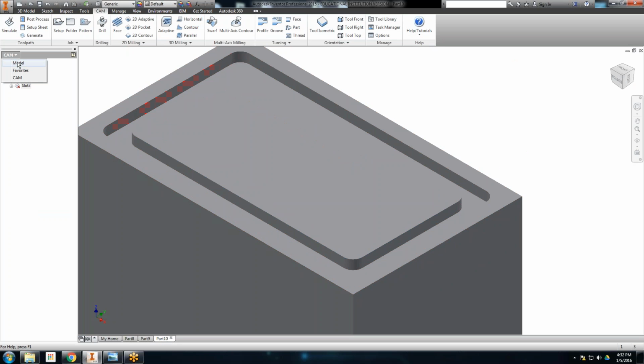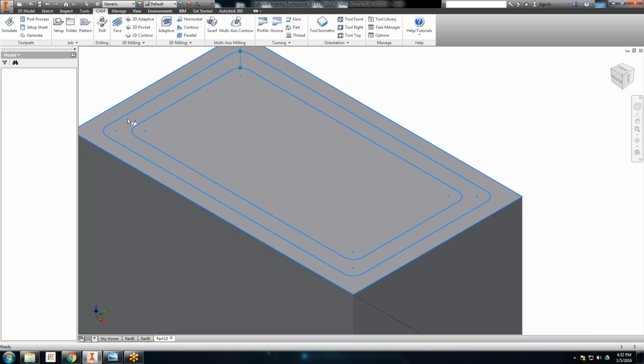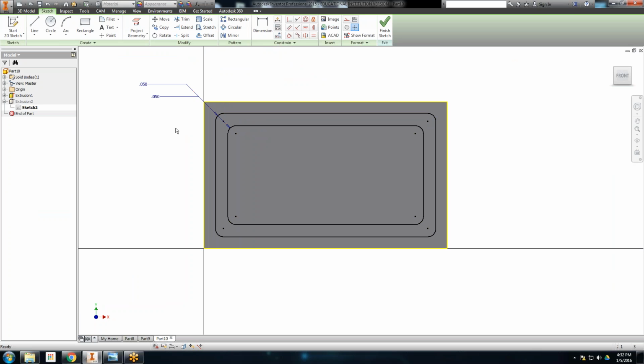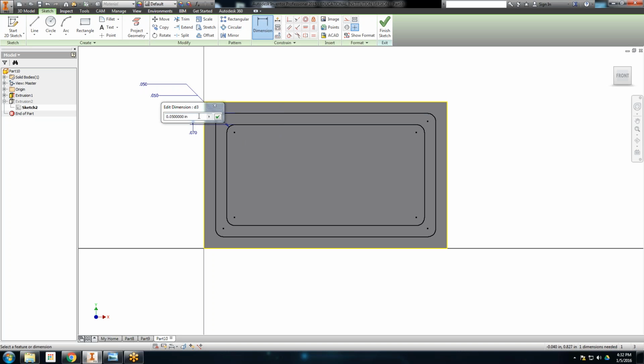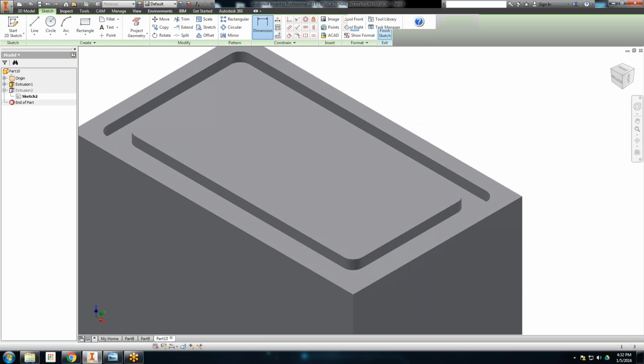So when you redesign it, is it just the offset command that you're using to make sure that the two are matching? Well, if I was truly looking at it, if this was 0.07, then this fillet here should have been plus 0.07. That should have been a nice smooth contour around there. So whatever this outside fillet is should be this original fillet plus the distance in between the fillets. That defines a true slot.